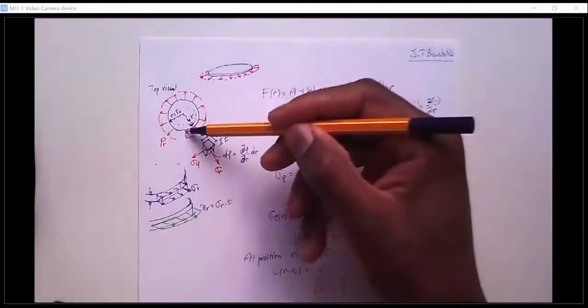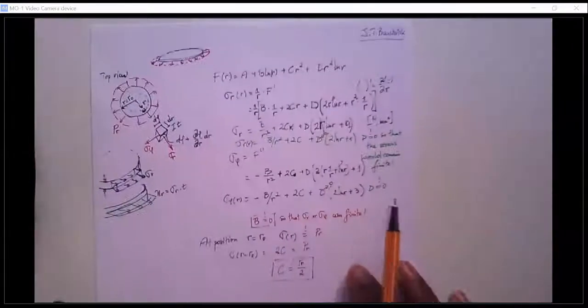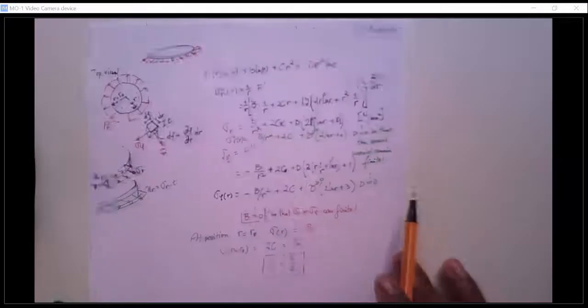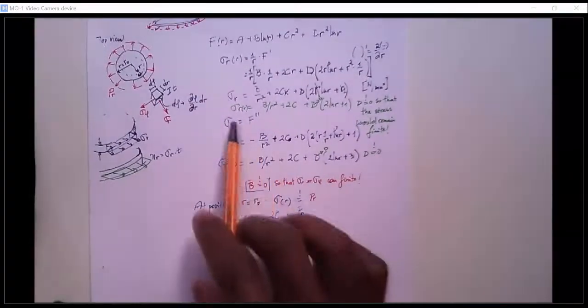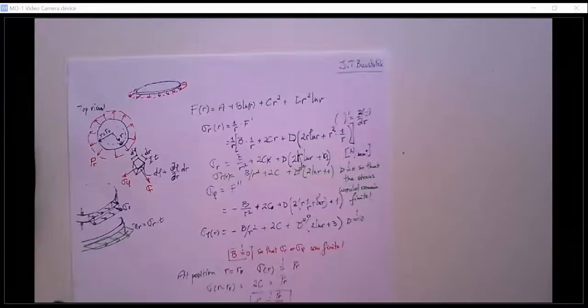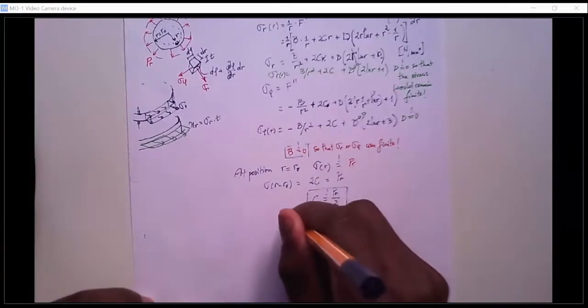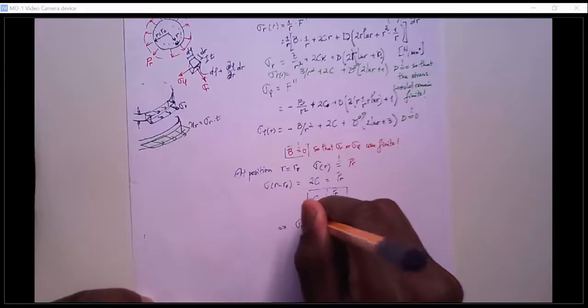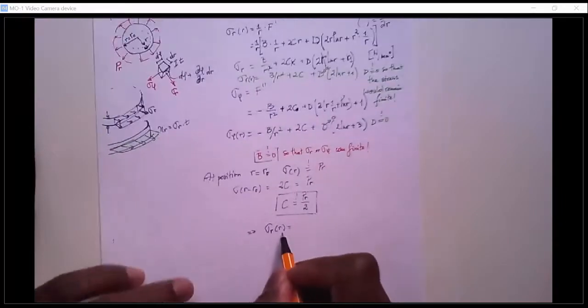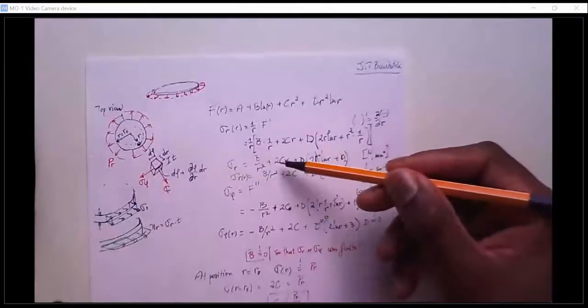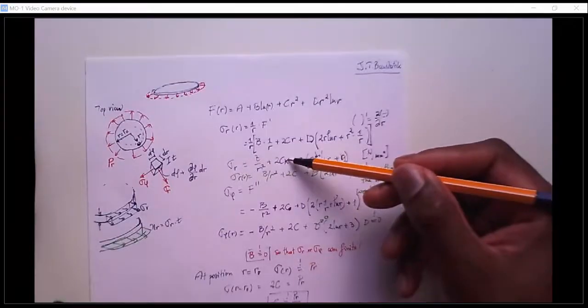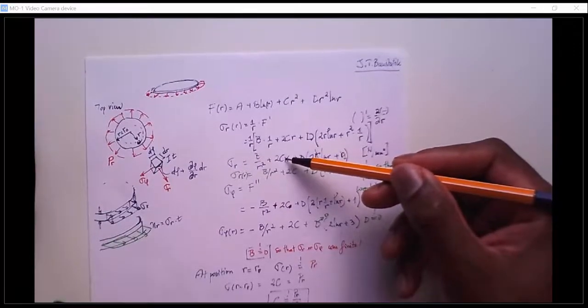Okay, what happens inside can be calculated with our formulas, and it basically remains, you see here, with the value of c, we can figure out what sigma r actually is for any random position of r, because you can see in this case there's no function of the radius anymore, so the stress in the radial direction is basically gonna be constant.